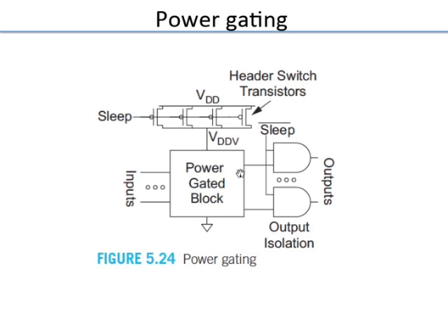The other thing you have to watch out for is these outputs. See, when you shut off this power gate, what happens to this VDD V? Why V? Because virtual. It's called a virtual VDD. You can also have these power switches in the ground. Then that becomes virtual ground. VDD V, what happens to this VDD V voltage? Where will that voltage be?